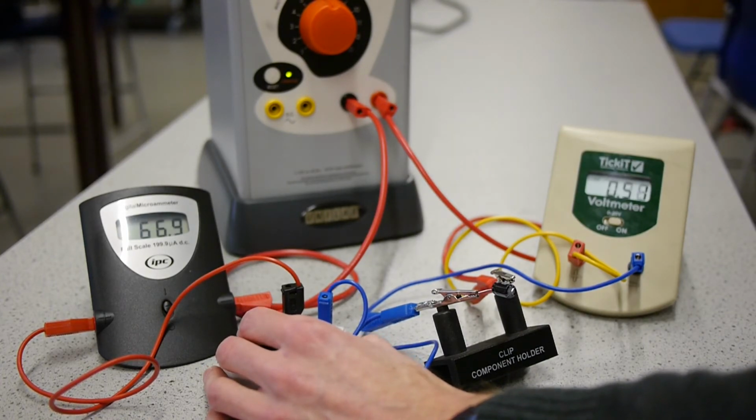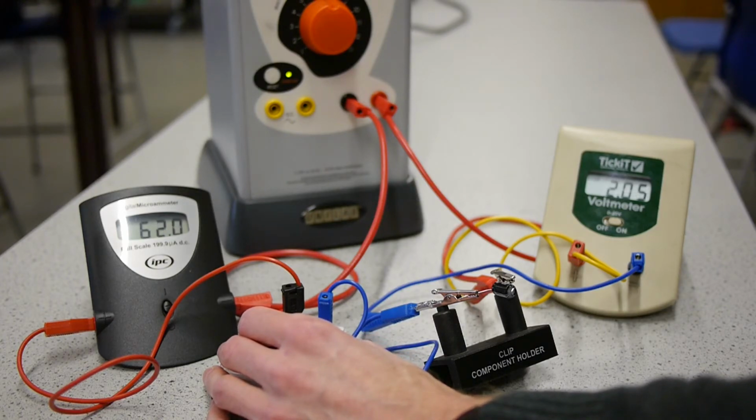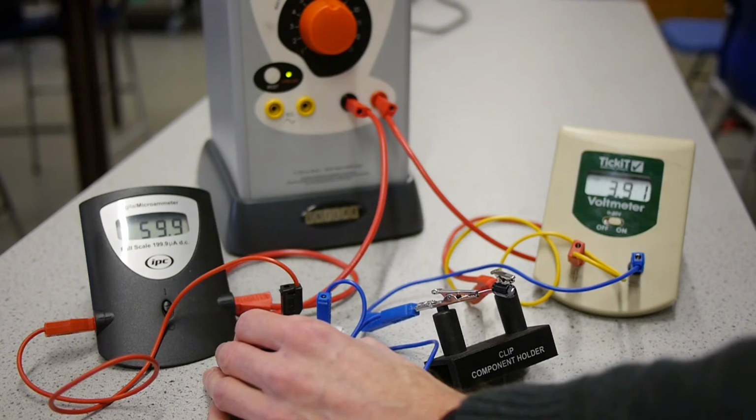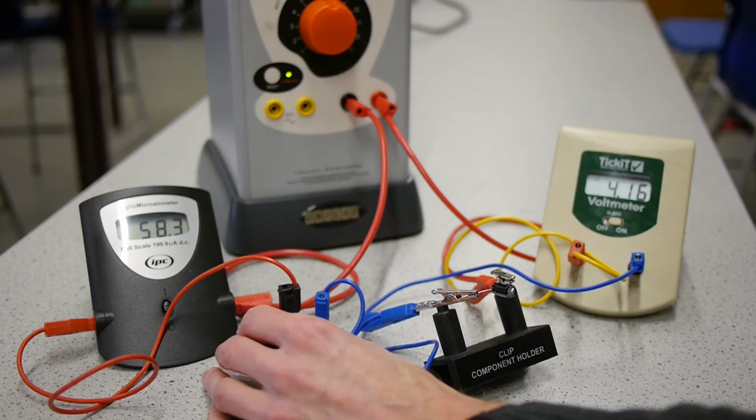Now that's not easy, but basically here we've got an initial current in our circuit of 62 microamps, and we've measured that earlier. So just short out the capacitor, just see what current would flow through this resistor. So I reckon it's about 62 microamps, and we turn on the power supply then, and what I'm going to do here is just keep reducing the resistance. It's not easy, but sometimes it'll go a bit above, sometimes a bit below, but we're going to maintain an average charging current of 62 microamps all the way through until the capacitor has fully charged.